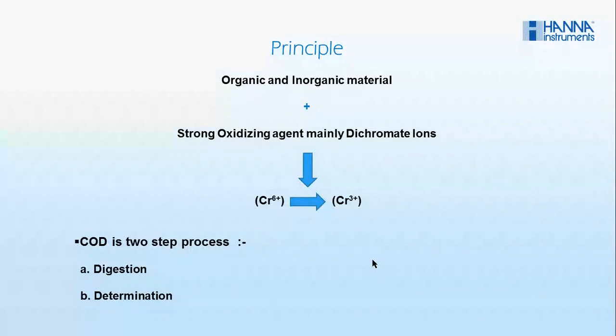It is normally measured in both municipal and industrial wastewater treatment plants and gives an indication of the efficacy of the treatment process. COD is measured in both influent and effluent. The efficacy of the treatment process is normally expressed as COD removal, measured as a percentage of organic matter purified during the cycle. COD has further applications in power plant operations, chemical manufacturing, commercial laundries, pulp and paper mills, agriculture and animal waste runoff, environmental studies and general education also.